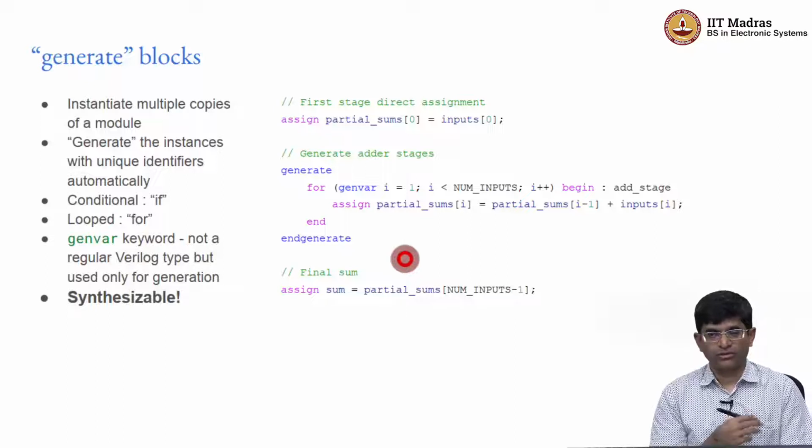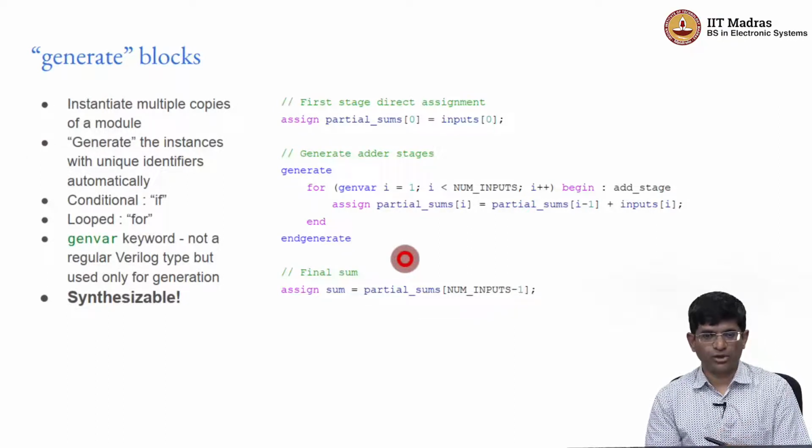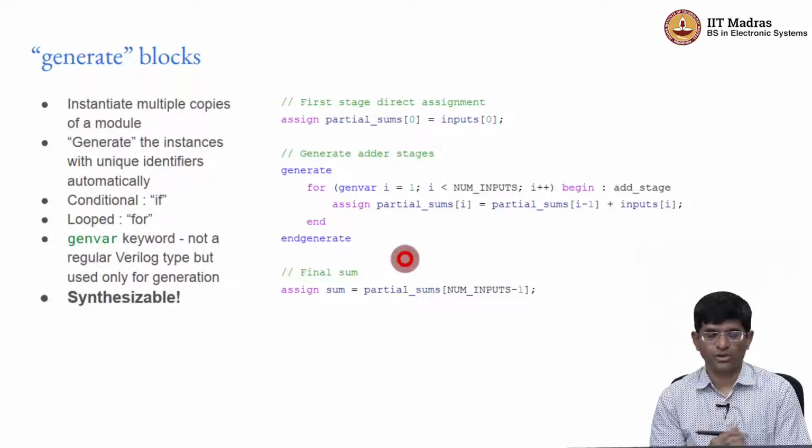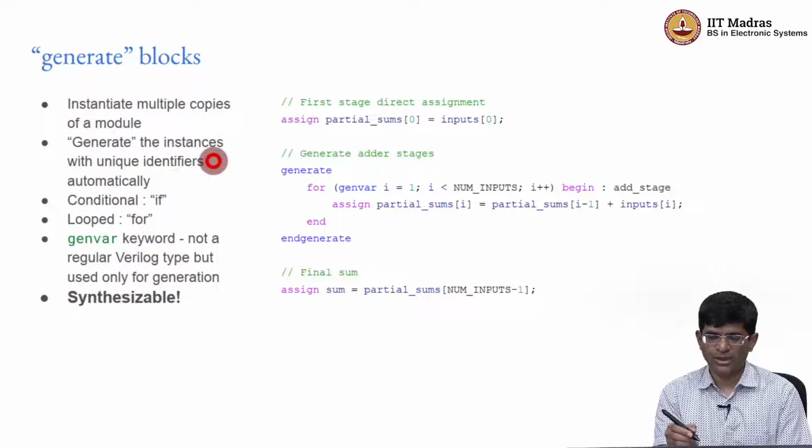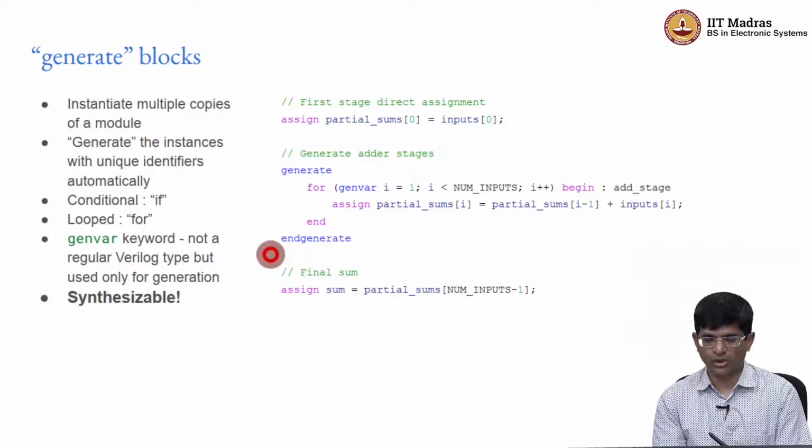Now the for loop that we saw over there was a very simple form of for loop. A more potentially useful approach in Verilog is this notion of something called a generate statement. Generate statements can be used to actually generate multiple different instances of a block. An example is over here. I have a generate and endgenerate block out here, inside which I have a for loop. Now this for loop looks like a regular for loop, except that this is called a genvar. It's not an integer.